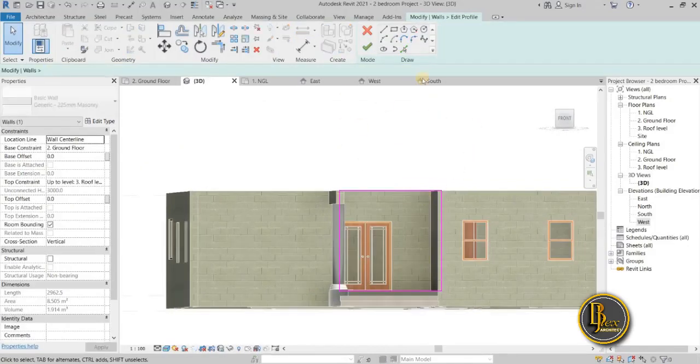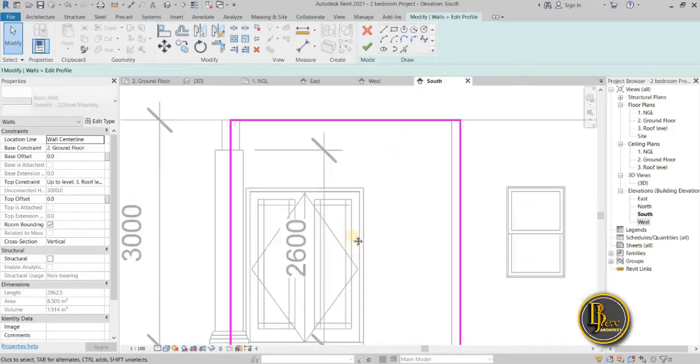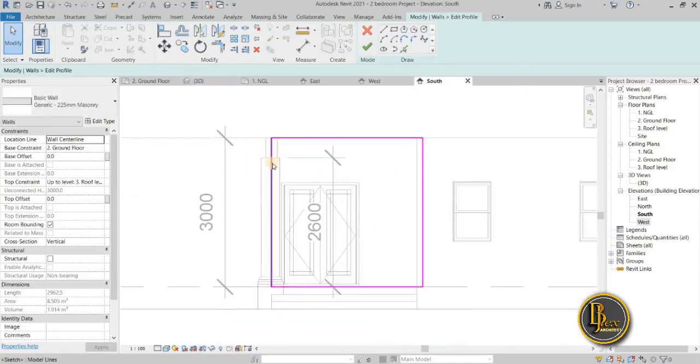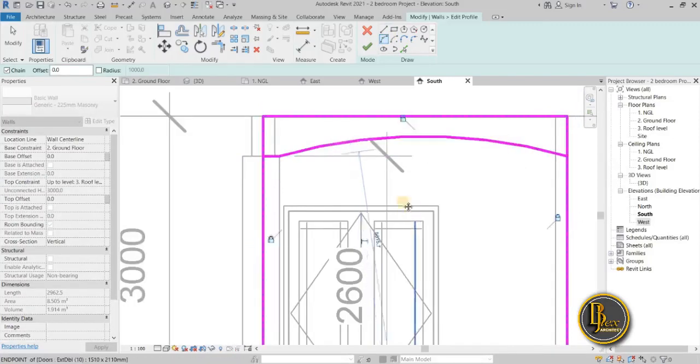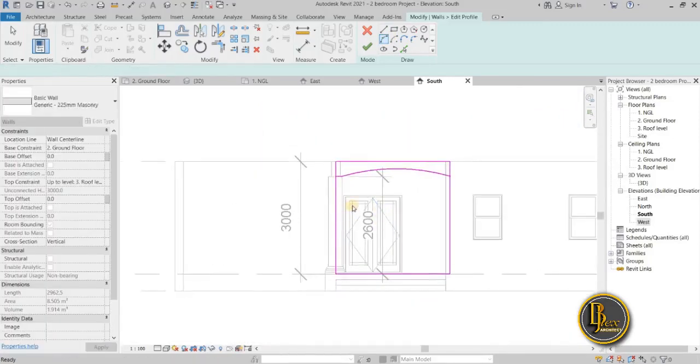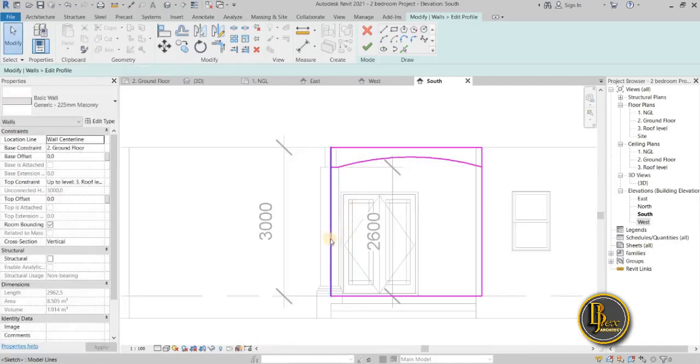Okay, then that same thing we did in that other one, but this time you can actually create an arc. If you don't want the beam to be straight, for example, but you want an arc in front of the building, just go to this. Let's create so that the arc won't be sharp. Let's create the first edge. Alright, then create another edge somewhere. Take an arc here, pick that line, then take it to the other line, then it will create an arc for you. Then let's see. Arc is actually slim, but this is just for reference purpose. I want us to use a straight beam.